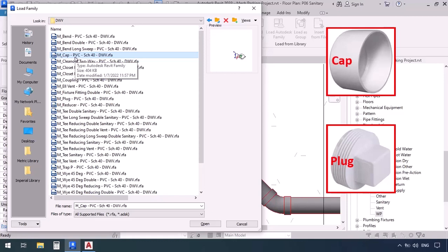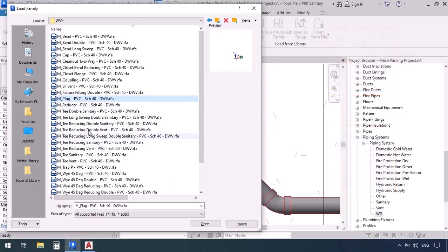All this cap does is cover. Now we have another thing called a plug. A plug has some kind of screw shape to it and goes inside the pipe. So in case it was necessary, we can just take it off, put in the spring, place the cleanout, and put the plug back in. So it is better that for cleanouts we use plugs.